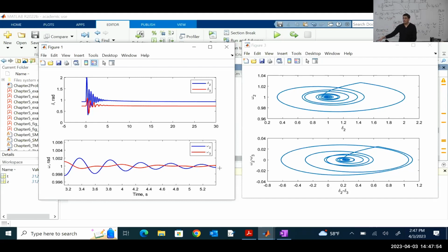Okay, guys, so I'm going to leave this here. I want you to take this code and play and find the critical clearing time. How are we going to do it? We apply it in the same way as before. We're going to create a vector with different clearing times. We will invoke this solver in a loop and simulate all the solutions. When we determine instability, we're going to start narrowing down the critical clearing time until we find the right time. And we can do that for two cases.